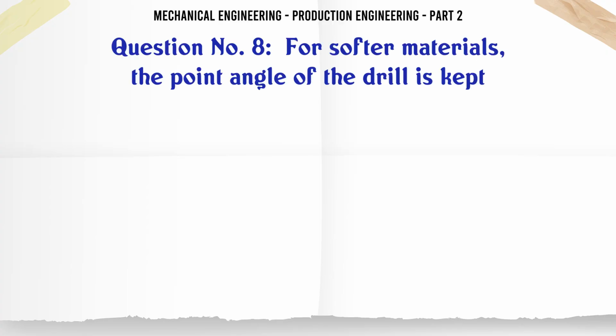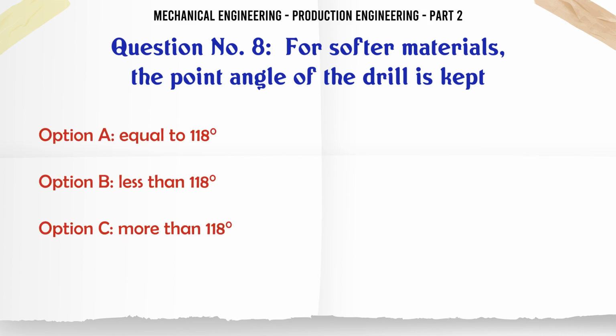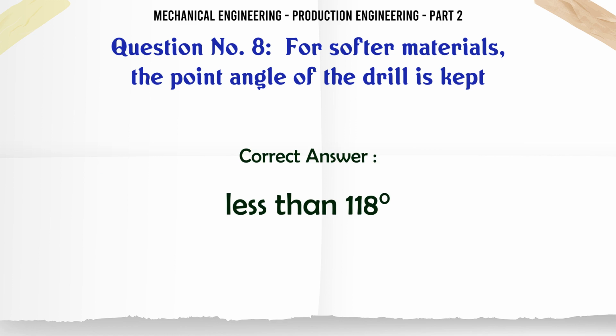For softer materials, the point angle of the drill is kept A. Equal to 118. B. Less than 118. C. More than 118. D. Any one of these. The correct answer is less than 118.